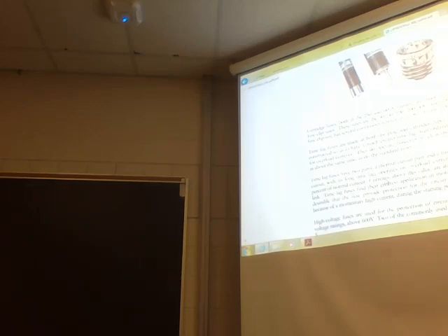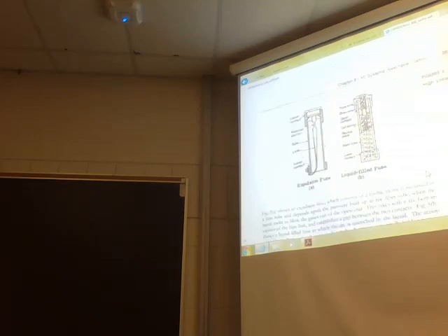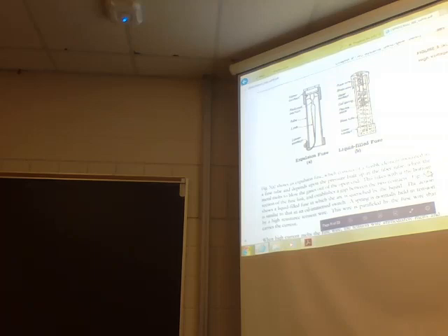High voltage fuses are used for protection of circuits and equipment with voltage ratings above 600 volts. Two of the commonly used fuses are shown here. Figure 5A on the left shows an expulsion fuse, which consists of a fusible element mounted in a fuse tube and depends on the pressure built up in the fiber tube when the metal melts to blow the gases out of the open end. This takes with it the bottom section of the fuse link and establishes a gap between the two contacts.